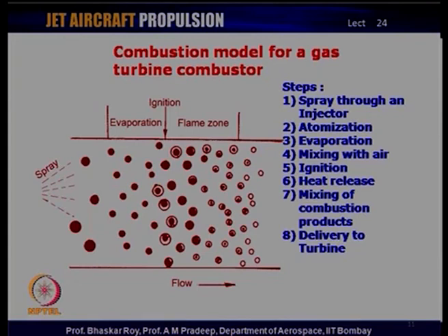and following that comes the mixing of the evaporated liquid fuel with the air. The evaporated fuel must mix with the air in a uniform manner. Once the evaporation has been completed and air and fuel have been mixed in a certain known proportion, the ignition is initiated, and once the ignition is initiated, that mixture of air and fuel starts burning.